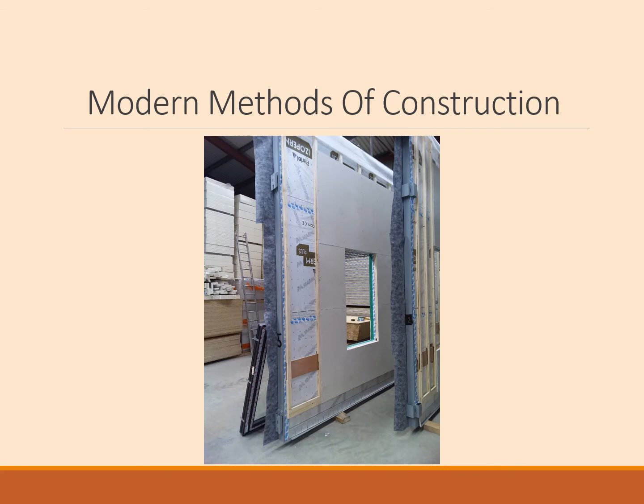Here we have a panel being assembled in a factory. It's made from light gauge steel frame, which you can see here. You can see fixing brackets top and bottom, here and here. The window, which is here, will be factory fitted over here. The ends, which you can see this area here, won't be completed until it is assembled on site and any necessary fire stopping at the junctions and application of air tightness membranes have been applied.